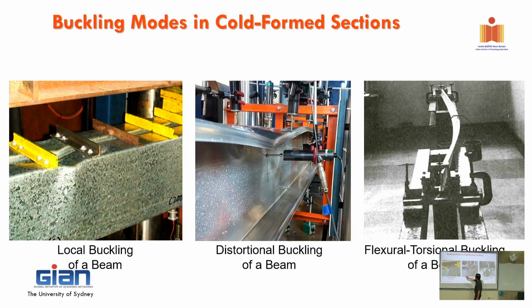The first one here is my test when I did my PhD, where I tested the channel section in bending. So this is a channel, but when I test it, I put it toe to toe, like this one, okay? And I put a strap on top of that. The spacing is quite small. And then we test it in bending. And it buckles, you can see, that is local buckling.